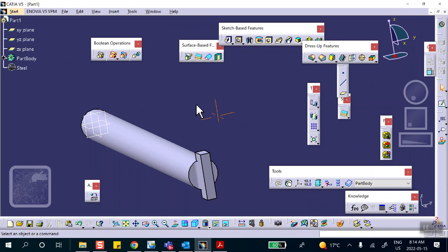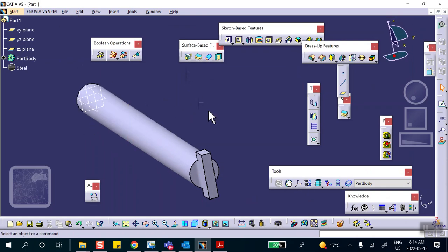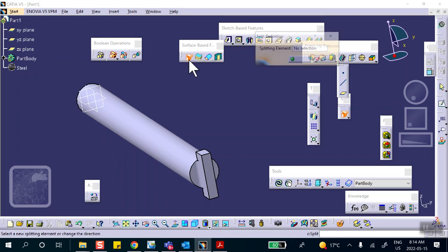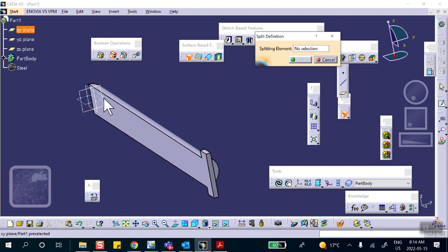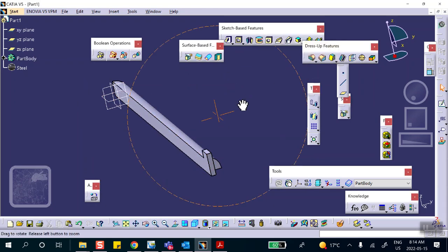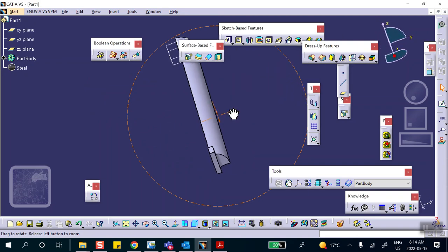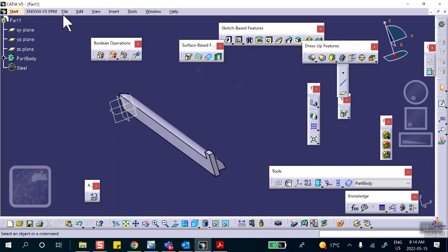And this problem has two planes of symmetry, so I'm going to cut it. Let me put this thing in. Yeah, let's cut it. Here's the split. Katia calls it split, doesn't call it cut. Let's cut it with the vertical plane, and it doesn't matter which side we pick. And then let's cut it again with the horizontal plane. We'll keep the top part. Okay. So this is 1/4 of that model, and I'm going to save this thing.